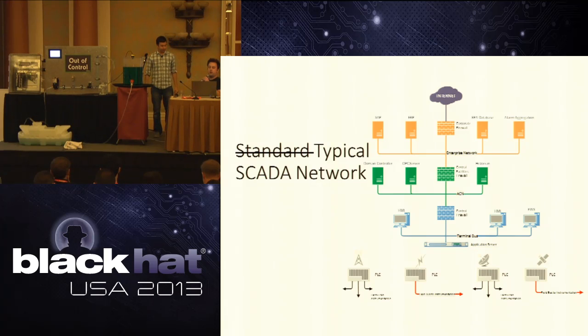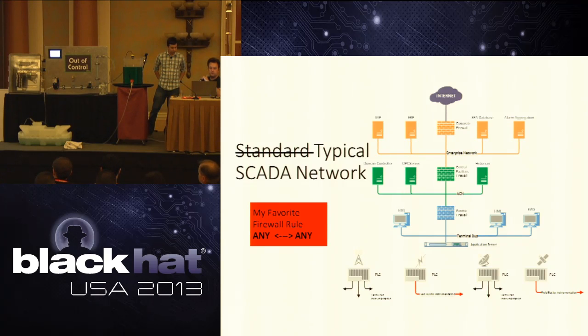Yeah, and this is a typical SCADA network. This is the recommended network architecture, where we have multiple firewalls in place to segregate the traffic types. However, if we move on to our next portion here, a lot of the firewalls that are implemented are really just put in place because somebody needs to comply with a standard, and they end up leaving their firewall just allowing all traffic to pass, which isn't really a firewall at all.